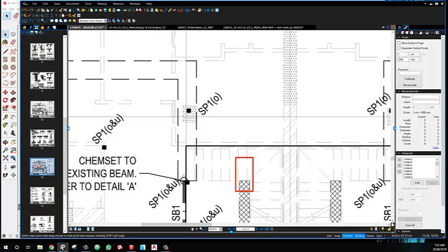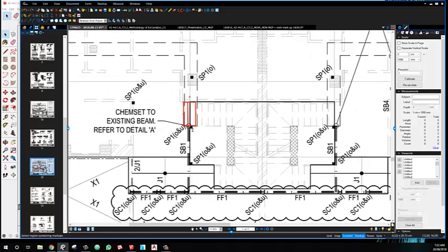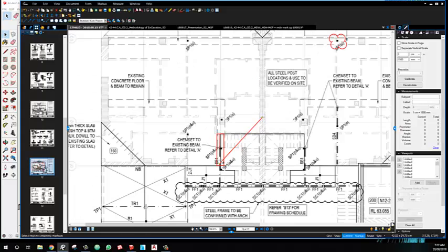So we need to extend this steel beam up to here, up to the alignment with the wall, and cut this beam, which in fact is cut all the way to here, because this is the corner of the building. Now there is a hole, so this beam is not supporting anything, because all this is going to be demolished. So just have that in mind.